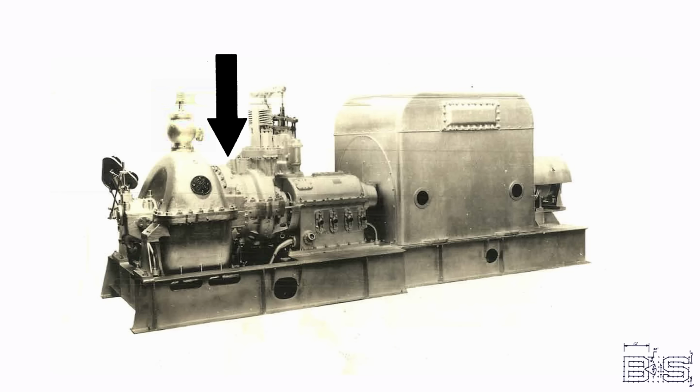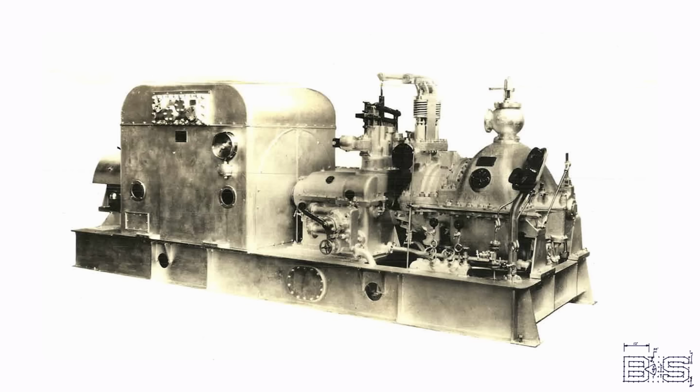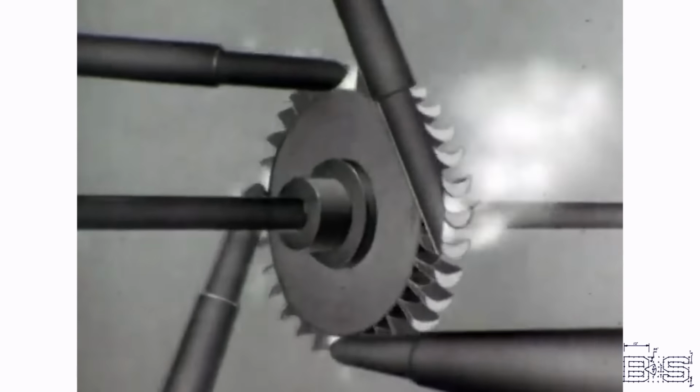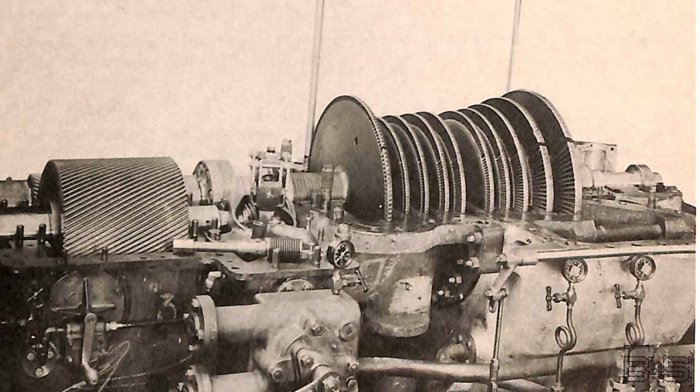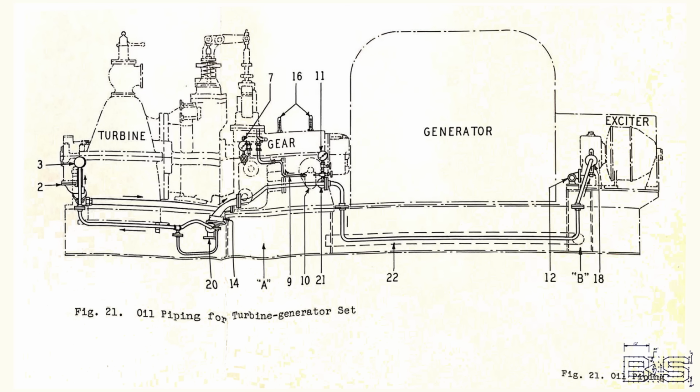In addition to the main engine turbines that propel the ship forward, machinery rooms 1 and 3 also have two smaller turbines that drive AC generators. These are called turbine generators, or turbo generators for short. The turbine uses 545 pounds of superheated steam expanded through 10 stages of blades. The turbine's rotational speed is controlled by a governor. The reduction gear reduces the speed to 3600 RPM to run the generator.